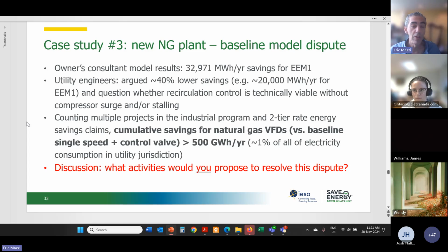And usually one way to reduce the uncertainties there is to say, well, let's just go find some inefficient system, whatever it is, like with water treatment. Let's just go find some similar water treatment processes that are pumped, and you could do some measurements on that process and model it. And then you can use that activity to inform what you would have done on the actual system that's undergoing M&V if there were questions.